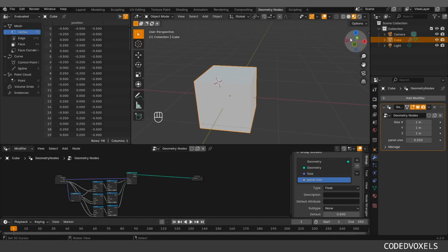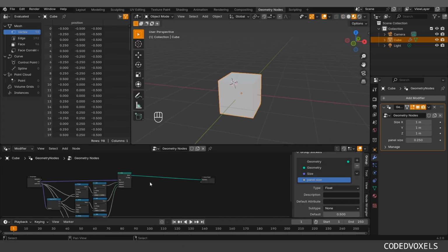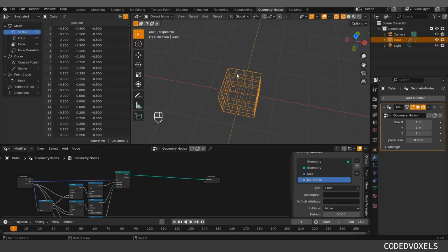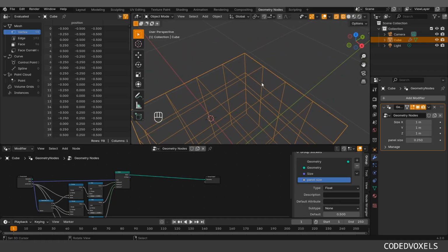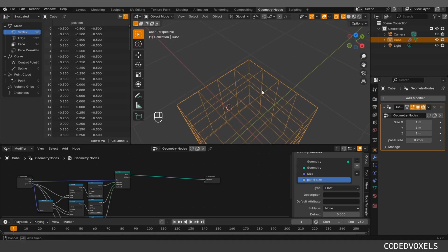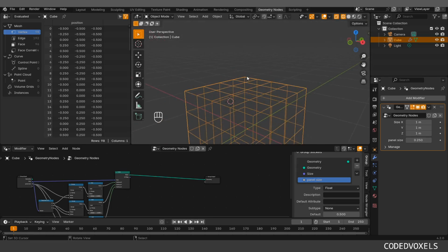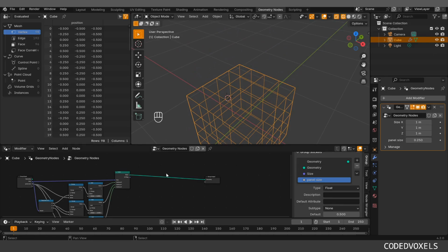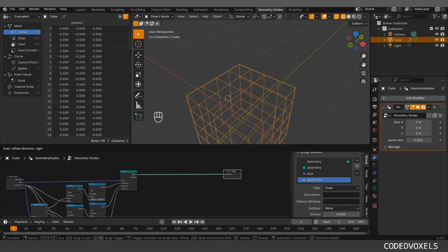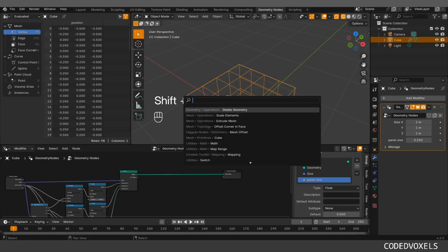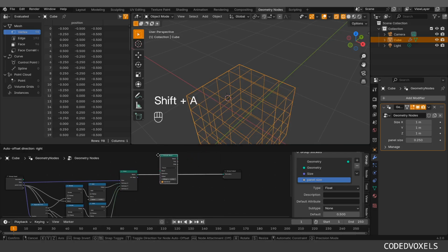All right, now the next step after we got our panel size is we're going to grab each one of these faces and we're going to inset it and delete the middle part of the inset face, so we can have our perforated panel. And for this, we're going to do a quick trick. We're going to extrude, so Shift A, Extrude Mesh.